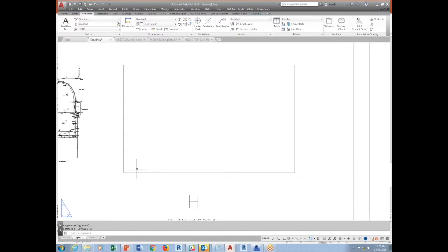Now you notice that in here, the line type just doesn't look right. So the first thing you want to do is check paper space LT scale. Okay, it's going to be 1 or 0. If it's 1, it means that it looks correct. Next thing you want to check is MS LT scale. It's 1, it's correct. And then LT scale. Let's see if it's 1. Is it correct? Yeah, it's because it's too dense. If it's too dense, then this is where you're going to say LT scale 0.1. So that's what's controlling it.